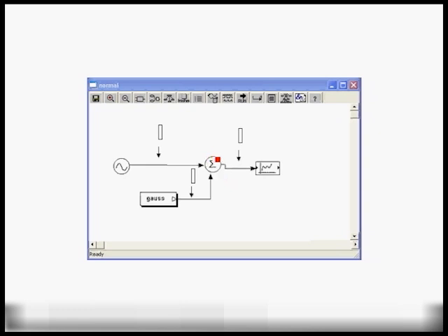In this case, the add block basically sees 128 samples from the sinusoid generator, 128 samples from the Gaussian generator, consumes all 128 samples, outputs 128 samples to the plot block, and this is very efficient. Let's take a look at what happens when you have feedback.